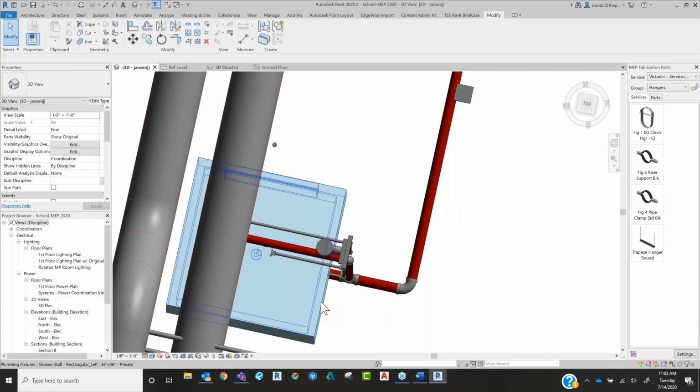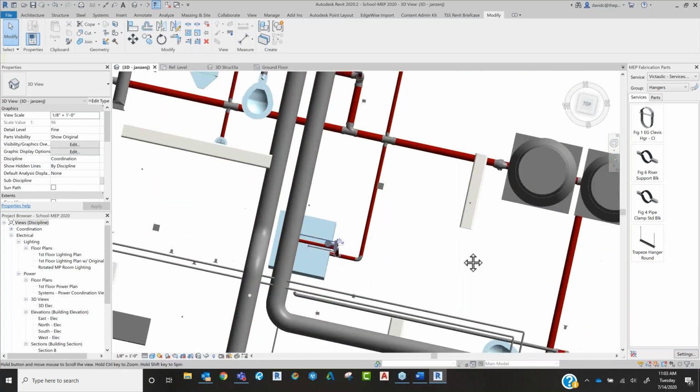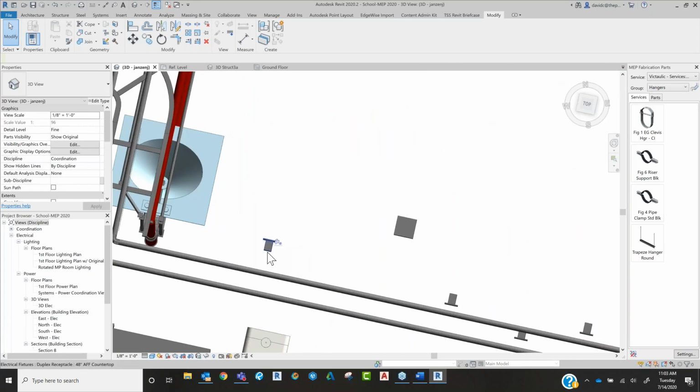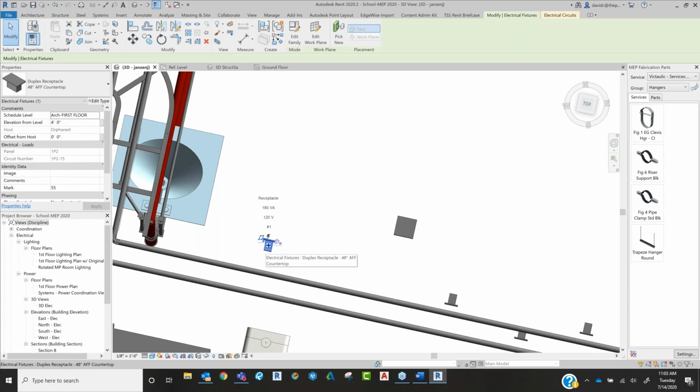So as I was saying about those occupancy sensors, if you have a lot of those things around the model, it would take a really long time to try and just grab every single one and lay out to them. I'm not doing all that. I'm going to go ahead, get into the family. I'm going to nest a point right inside of that family. And then right when I load it in, the family updates to have that point information inside of every one of them.